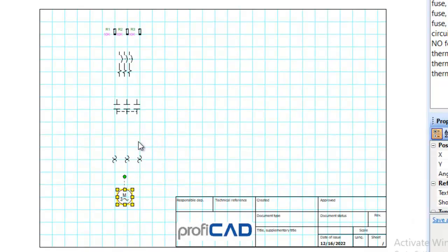Okay. So if you look at the orientation, you will see that I want to use this 3 line, 1, 2, 3, to run my line to my motor. So what I will need to do is to expand my circuit breaker to cover that line. Okay, so I've done that now. Yes. Then I will also expand my contactor just to make the work easy for all of us.